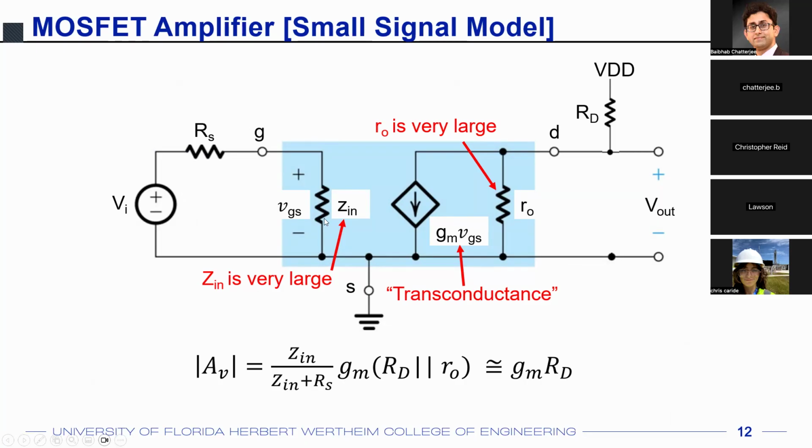Now you can probably just relate it back to the op amps that you learned in 3111, that op amps had an infinite input impedance. So you can probably guess that inside the op amp there are these MOSFETs with the gate of the MOSFET directly connected to the input of the op amp, and that is the reason why it has infinite input impedance. We'll look into that later in detail, but I just want you to think and relate with that concept.